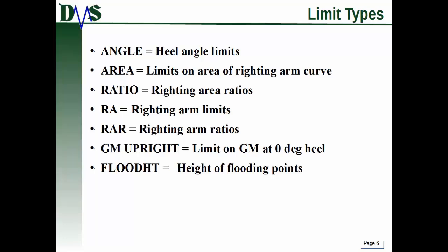We've got righting arm limits, so that's the actual GZ value as it varies with heel angle. RAR is righting arm ratios. And that's slightly different from ratio itself.